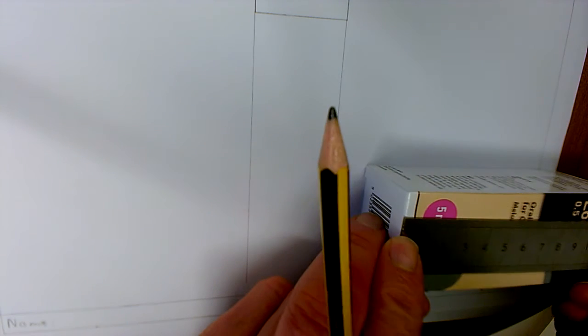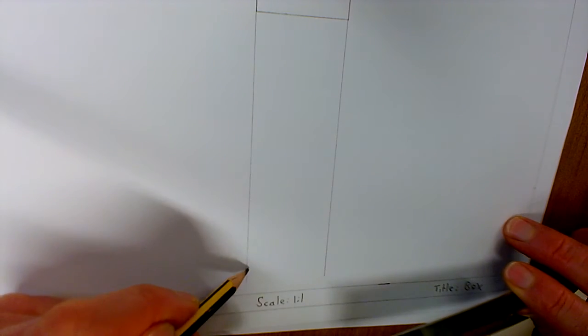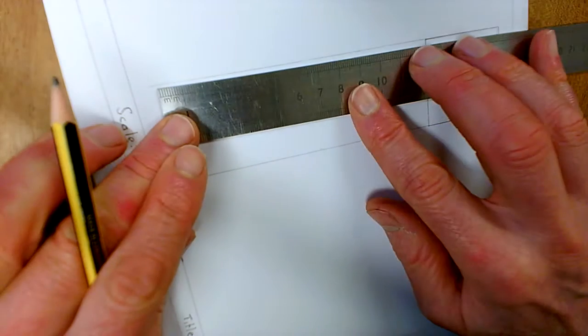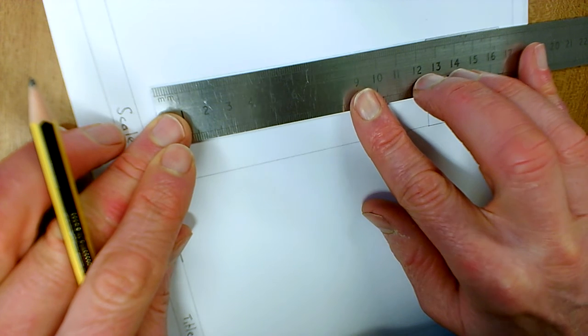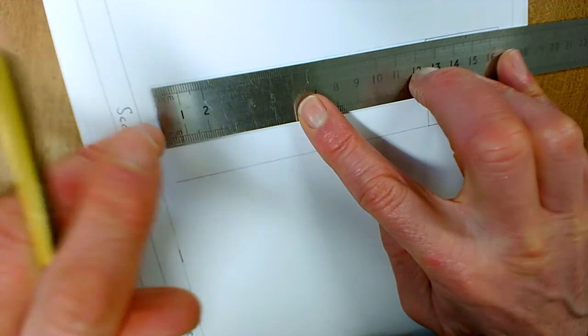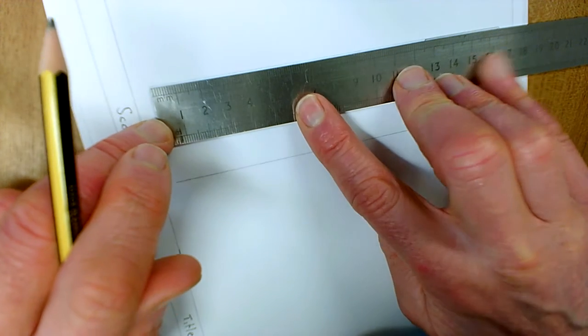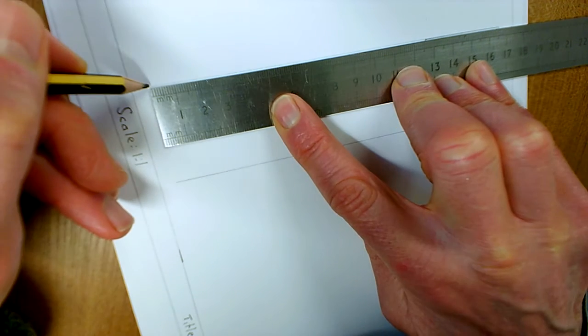I did say it was 115, didn't I? So the height of it is 115 millimeters. Again, don't forget, because we're doing it 1:1, it will be 115 on a piece of paper. So I'm going to start around about there. I'm going to get my ruler and measure 115, taking it down a little bit low, to about there, so it'll just about fit on. So 115 is there, and I'm going to draw directly onto that guideline, but a little bit harder.